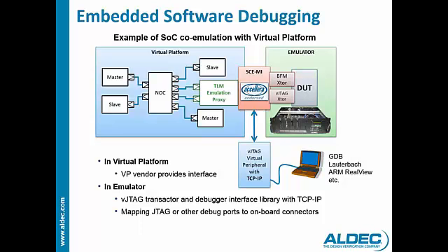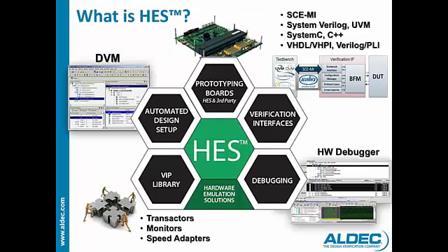We've got FPGA prototyping boards utilizing the Virtex-7, and currently testing the UltraScale FPGAs for the hardware platform. There's a design verification manager which controls all the interfaces and different tools depending on the tool flow. For example, the transaction level interface or bit level interface.